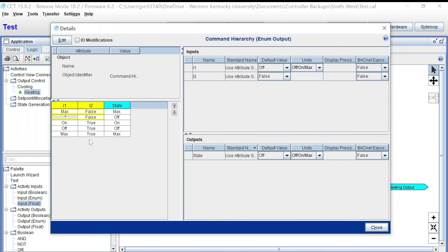What I would need to change, if I did not want that valve open for water flow or whatever when it went to max, I could change my logic a little bit to where, if the system was in max for any reason, and if I had my system command to false, then it would not do anything. It would not necessarily drive that valve open.